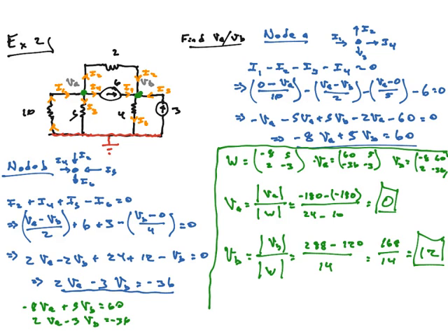So again, if this is part of some bigger circuit, connected to some other piece, and it's connected where the ground is, then maybe the ground isn't really at 0, maybe it's actually at 10 volts. So if that's actually at 10 volts, then VA is 0 plus 10, which is 10 volts, and VB is 12 plus 10, which is 22 volts. So always keep that in mind, especially if you're going to be doing this experimentally or in a lab. These theoretical calculations you're getting are relative to the ground.